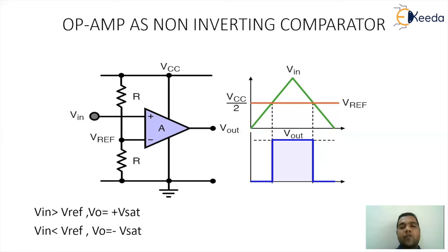Now this is the basic logic of a comparator, where the op-amp is working under open loop configuration. But all of us are aware that due to the impact of noise, there can be glitches or fluctuations at the output, or a false voltage can be generated at the output. To avoid such a situation, we arrived at the concept of the closed loop comparator, which was covered under the topic of Schmitt trigger. Schmitt trigger circuits normally operate as closed loop comparators.